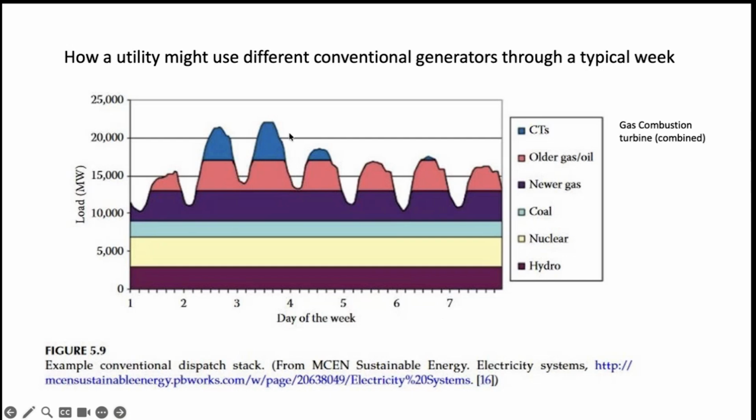And that's interesting. I would not put CTs up here. They wouldn't be peakers. I would use your older gas. This is where I would be using my combined cycle for an awful lot of the load. A little confusing, but I think you get it. Utilities have to figure out which mix they want to do, and ERCOT is dispatching on this basis.